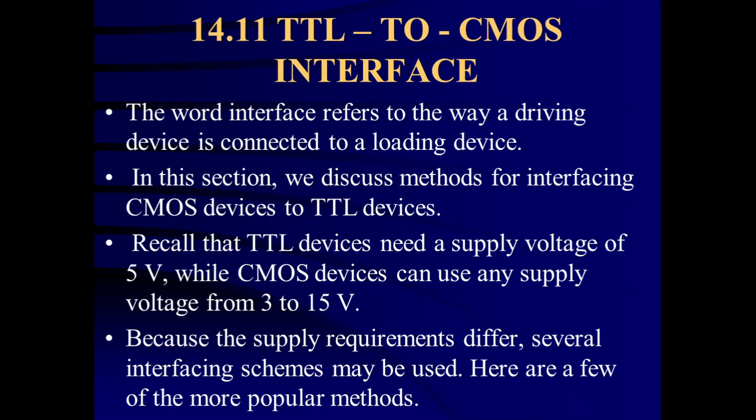So, if we connect the output of the TTL gate to the input of the CMOS, then in what various ways can we make this interface? That we have to study here. There are different methods for that, and we are going to learn them. We are starting with section 14.11, TTL to CMOS interface. The word interface refers to the way a driving device is connected to the loading device. In this section, we discuss the method of interfacing CMOS devices to TTL devices.